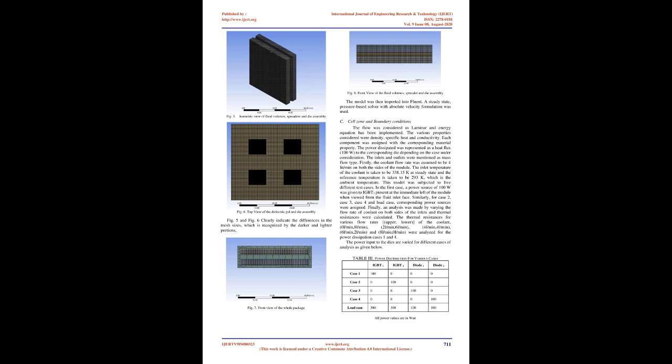This model was subjected to 5 different test cases. In the first case, a power source of 100 W was given to IGBT1 present at the immediate left of the module when viewed from the fluid inlet face. Similarly, for case 2, case 3, case 4, and the load case, corresponding power sources were assigned.